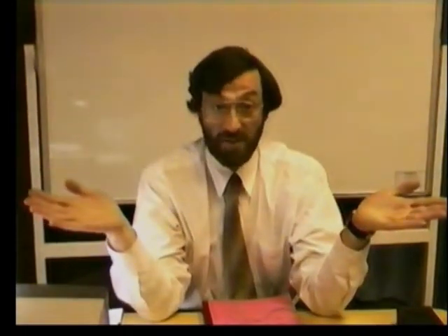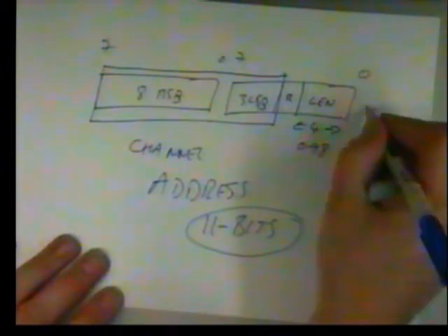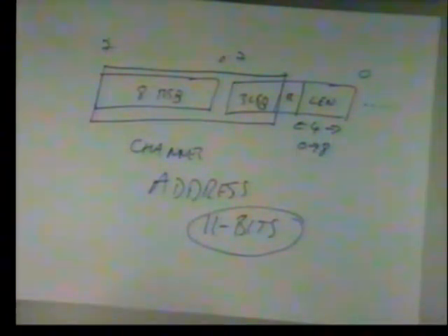Now what that field is for is to tell us how much data follows. And as I've said, the whole purpose of CAN bus is to pack it up into small bits of information. The maximum amount of data you are allowed to transmit is 8 bytes of data. It's not very big, but that's usually more than adequate for most real-time systems. Quite honestly, long packets will take too long to transmit. So the way this works is that the length field is a number from 0 to 8. Anything greater than 8 is illegal, and that tells us how many data bytes now follow that particular channel header.